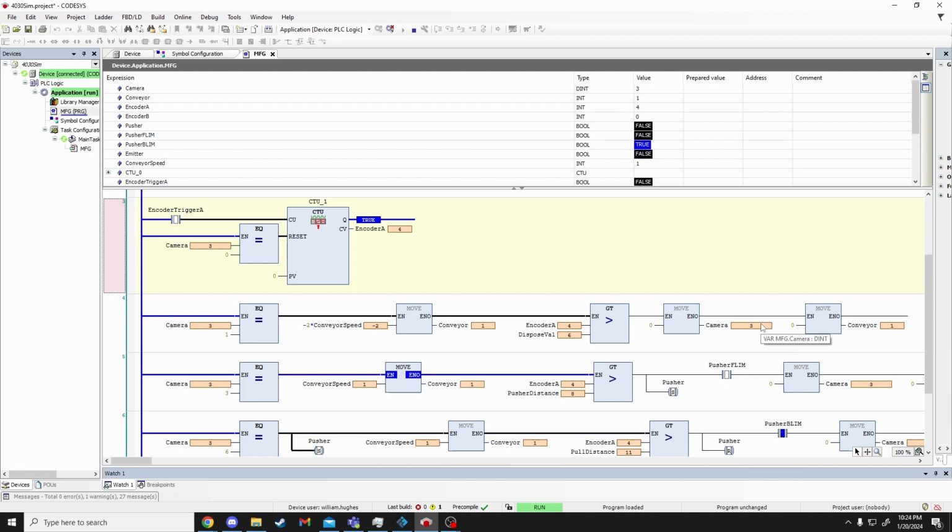Because if you don't reset the conveyor value at the end of each sorting process, it'll give you some weird behavior. It'll still be running. It'll pull back a part that was supposed to be going forward, or it'll push forward a part that was supposed to be going backwards. So it's best to just control the system and stop that conveyor belt between each part.